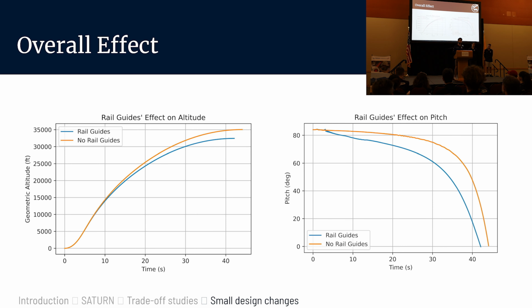Having implemented this in Saturn, we found that the effects were both far more wide-reaching and higher in magnitude than we initially expected. Firstly, we have a dramatic increase in our axial CD between 4 and 12% as a function of Mach number. So at our max Mach number, this is equivalent to an additional mass of 2.5 kilos.